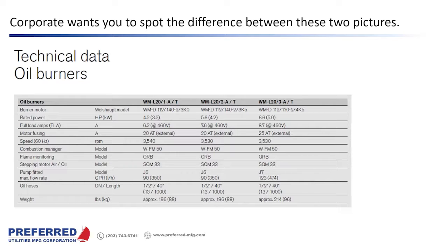If they say they're only going to run 2 burners at high fire, so only size the transfer pumps for 2 burners, I would resist that, because in most places in the United States, oil is a backup fuel. So they're only going to be burning oil if there's an emergency. And if they're in some kind of an emergency, more often than not, they're going to be needing a lot of steam out of the boilers, and they might need that third burner to go to 100%.